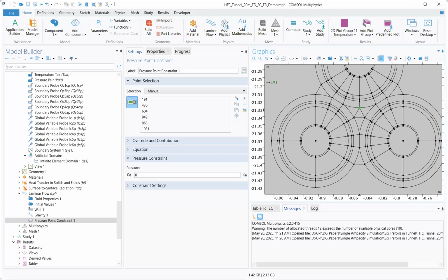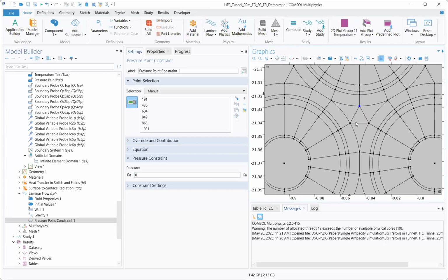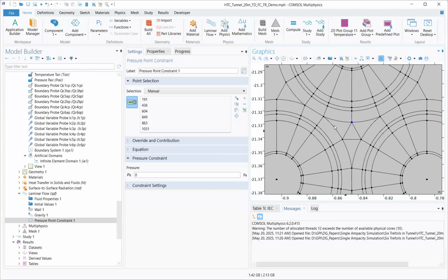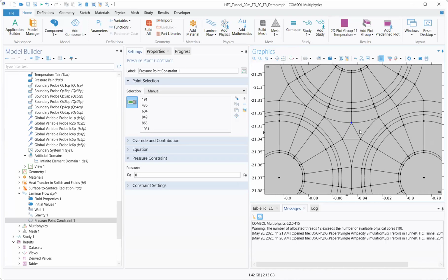In this region, there is really not much air moving, first of all, because the temperature is pretty much uniform and the air is trapped. So this region is not really important, right? But it's important for convergence. That's my point. It's not really important for affecting the final result, but it's part of the model. It affects convergence. So we need to manage this.